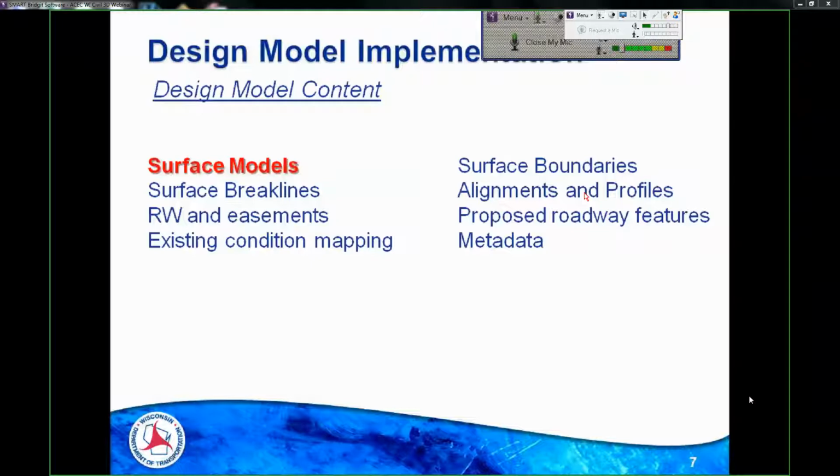There was also an unexpected use that we thought was pretty creative, or at least a positive development. They can use the existing ground surface model that we give them for early site reconnaissance. For earthwork bidding, one of the principal components of that cost equation is haul distance, right? The source of materials and where that material is located affects haul distance. So they're able to do early site reconnaissance. Our existing ground model, especially the photogrammetric collections, covers a wider swath of existing ground than the project limits. And so we're picking up all the property that's adjacent to the project.